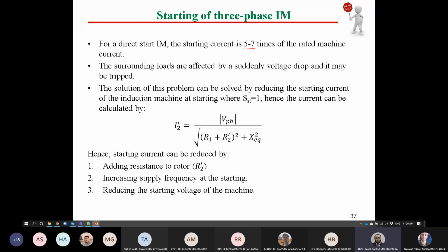In the starting, guys, if we represent here the RMS value of current, I root mean square with time, you may find that the current at starting is high, and after certain cycles it will be like that or even lower. So here, let me redraw again, please. Sorry.